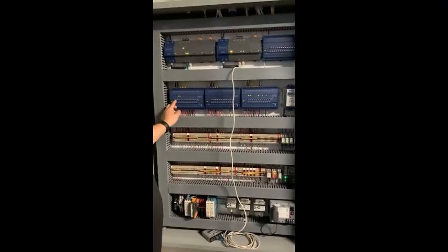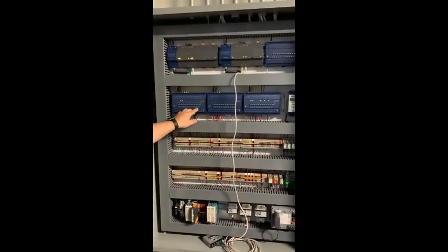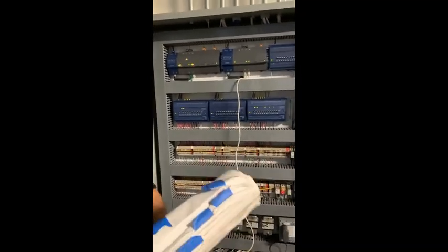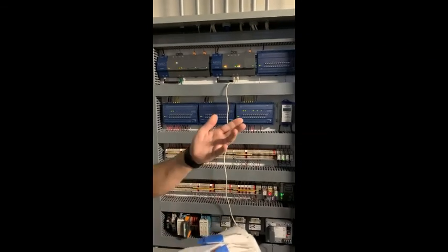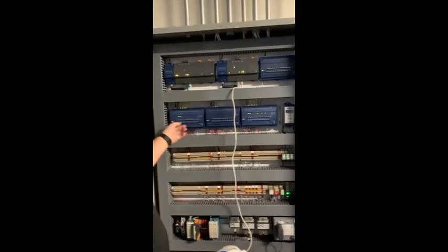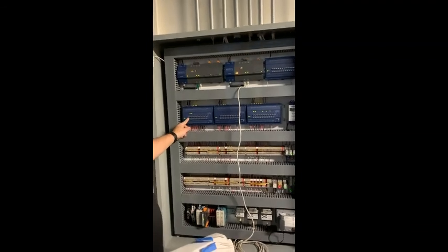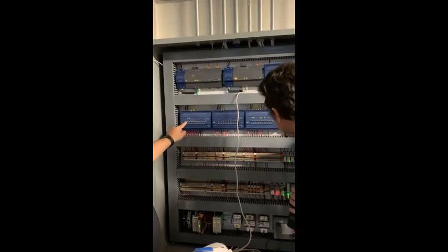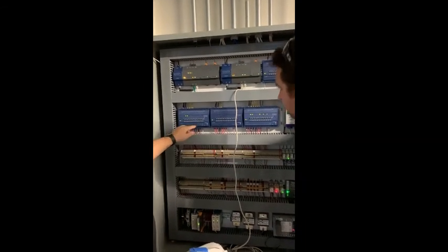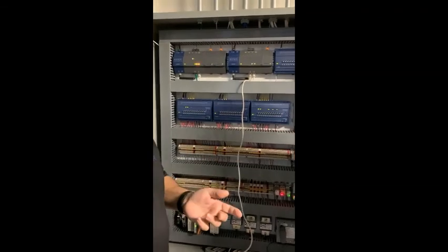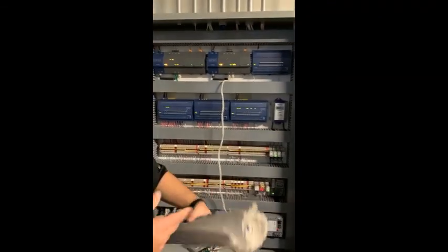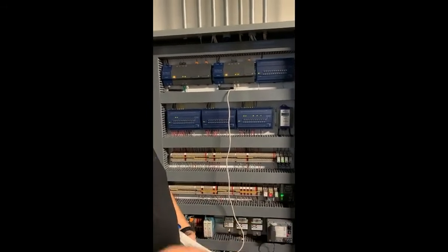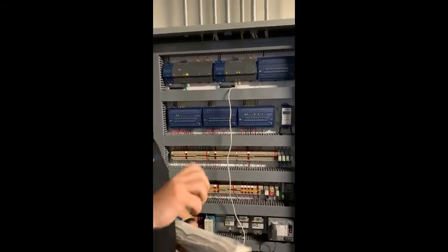So here, if you know what each output is, say you went in the code and looked at the controller and said, hey, I know output number 1 is for a fan. So here you could actually turn these inputs on and off with these hand switches. And if it's a digital, say a fan command, it's an on or off. So we're sending out power to a relay or not power. But for say a valve where it's modulating, it's a signal.